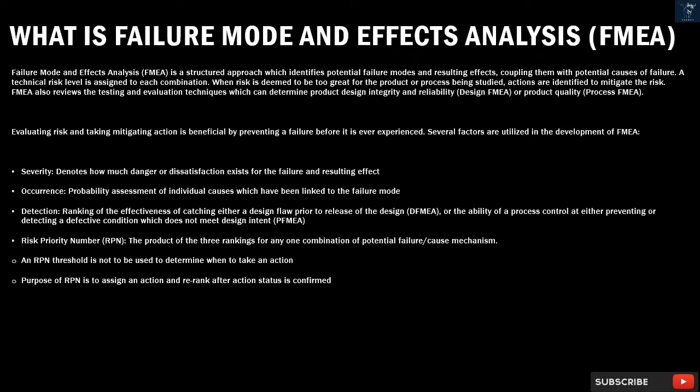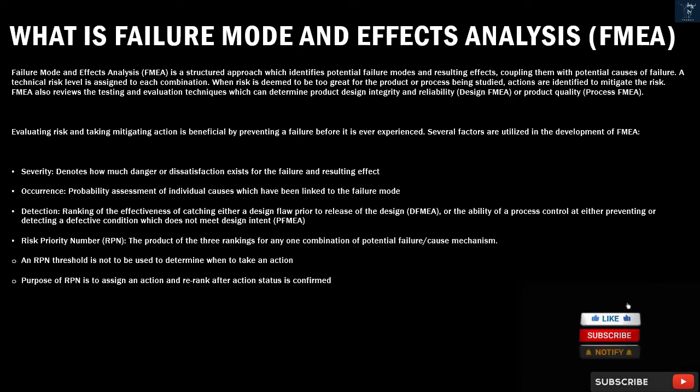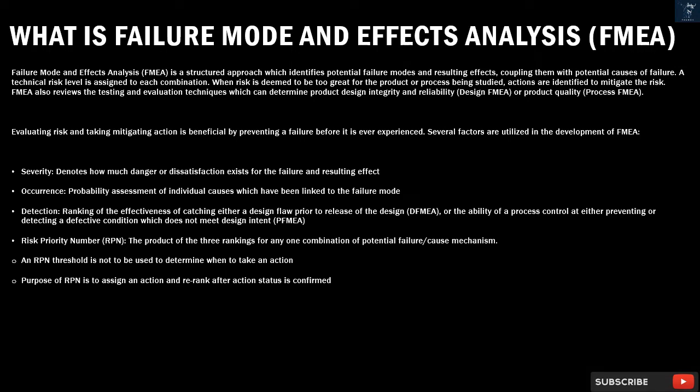What is failure mode and effects analysis? FMEA. Failure mode and effects analysis (FMEA) is a structured approach which identifies potential failure modes and resulting effects, coupling them with potential causes of failure. A technical risk level is assigned to each combination. When risk is deemed to be too great for the product or process being studied, actions are identified to mitigate the risk. FMEA also reviews the testing and evaluation techniques which can determine product design integrity and reliability.